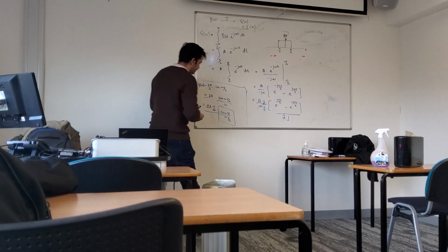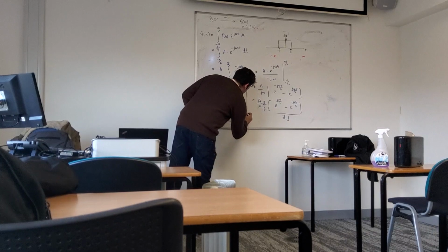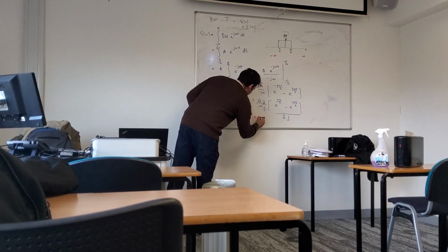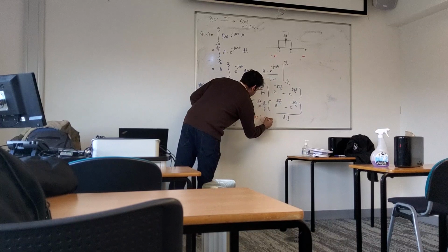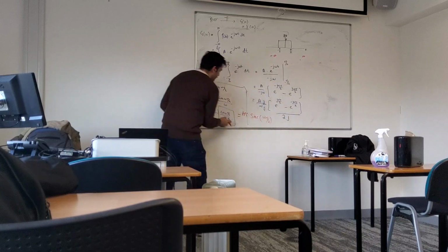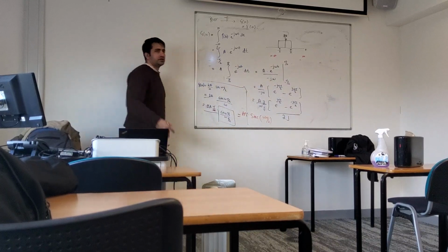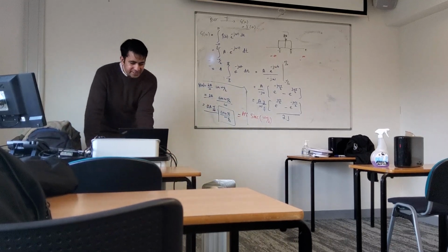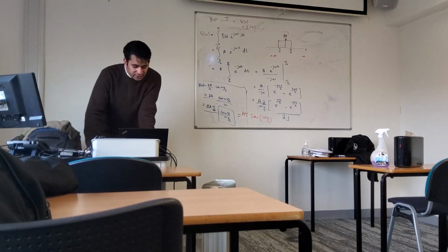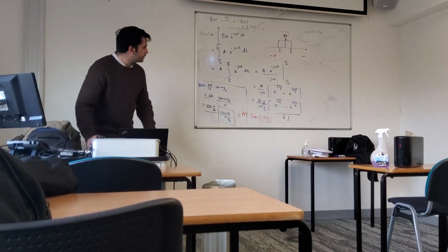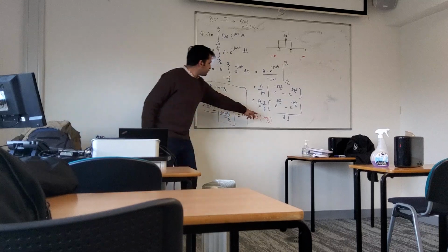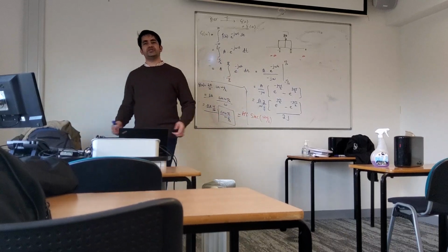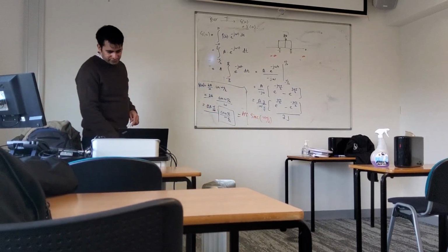So I can write this as a tau sinc of omega tau by 2. So I know sinc of omega tau by 2 is sine of omega tau by 2 divided by omega tau by 2. So it means that the Fourier transform for this case is a sinc function. And as I said previously, here your Fourier transform is a continuous thing. So based on the value of frequency, any frequency you can choose and it will give you a continuous function.